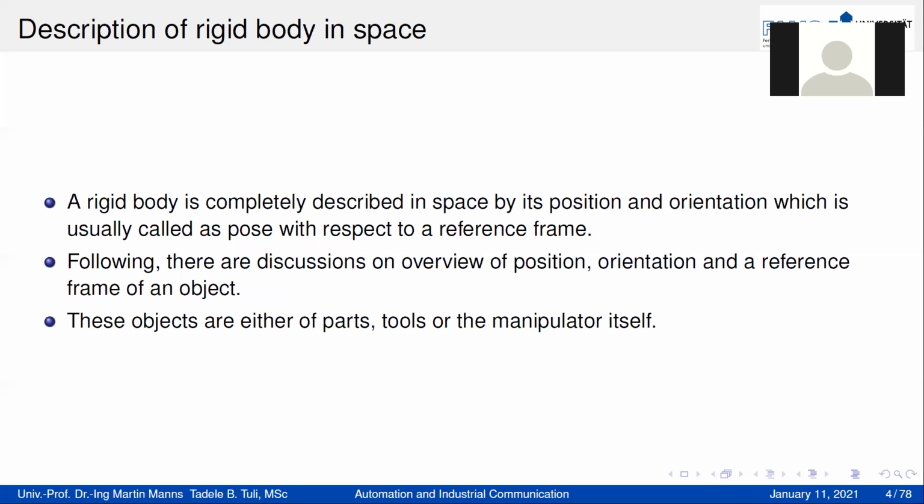In general, whenever you think about a rigid body, it's a body which doesn't deform or change position before and after a force is applied. So we assume a link is a rigid body. That means it doesn't deform under applied force. It will retain its original shape and its original position. As a result, the body doesn't affect the kinematics and dynamics. So we are only interested in the position of the joints and the rotation of the joints with respect to this kinematic chain. That's our preliminary assumption.